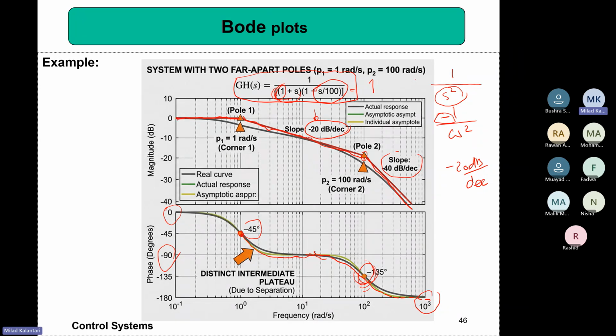So for this example, is this happening? When the gain is 1 or 0 dB, how is the phase? Phase is 0, right? So it's too far from 180 degrees, actually. When the gain is 1, the phase is 0, and we usually compare how far this phase is from 180 degrees, which is the start of becoming oscillatory.